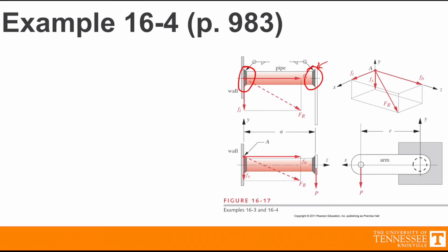Since if we put a 3/16 inch weld here, there's no bending occurring at the secondary weld over here. So since that's the case, there's less force per unit area on this weld. So putting a 3/16 inch weld will actually have a higher factor of safety than the weld against the wall.